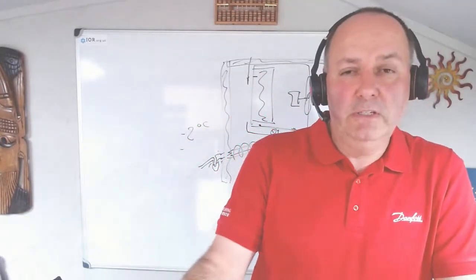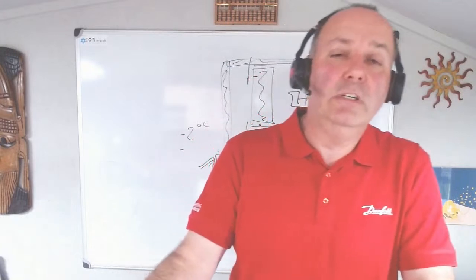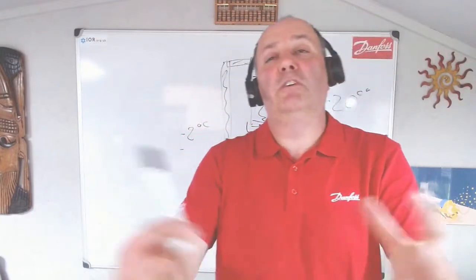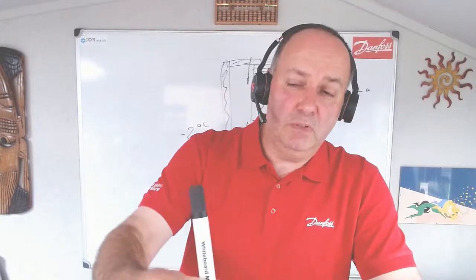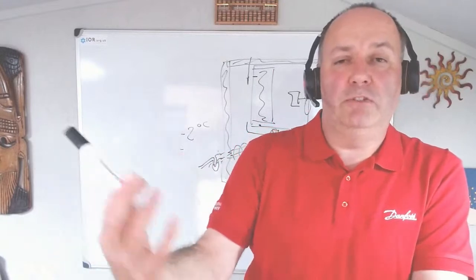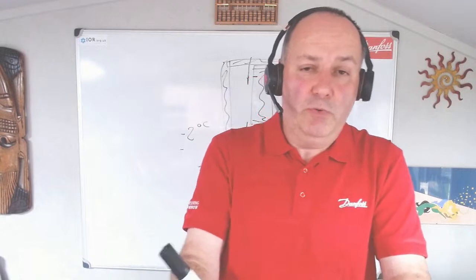Basically, an oil separator in a refrigeration system, it is what it says it is. It separates oil out of the discharge gas and returns it back to the compressor. By the function of the compressor, we move oil out of the compressor crankcase that's entrained in the refrigerant, and it gets pumped out. So the oil sep basically separates the oil out and brings it back to the crankcase where it's needed, because we don't really want oil in the rest of the system. We want it where the compressor is, because that's the function of the oil. It's a lubricating device.